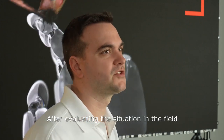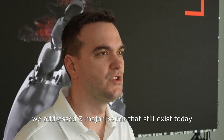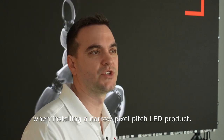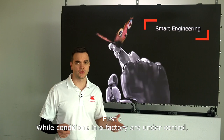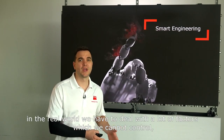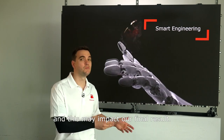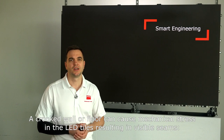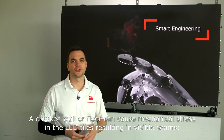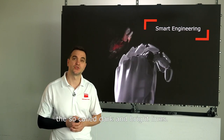After evaluating the situation in the field, we addressed three major issues that still exist today when installing a narrow pixel pitch LED product. First, while conditions in the factory are under control, in the real world we have to deal with a lot of factors which we cannot control, and this may impact our final result. A crooked wall or floor can cause mechanical stress in the LED tiles, resulting in visible seams, the so-called dark and bright lines.